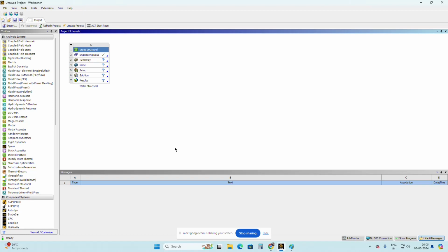You have to convert that three-dimensional structure into two-dimensional or one-dimensional. For example, hope you remember that stool structure, right? That plate you converted into 2D, and the legs you have to convert into one-dimensional elements. Sometimes you have to analyze the whole structure as three-dimensional. So in today's class, I'm going to teach you how to perform a normal one-dimensional analysis and how to convert that 3D structure into a 1D structure.